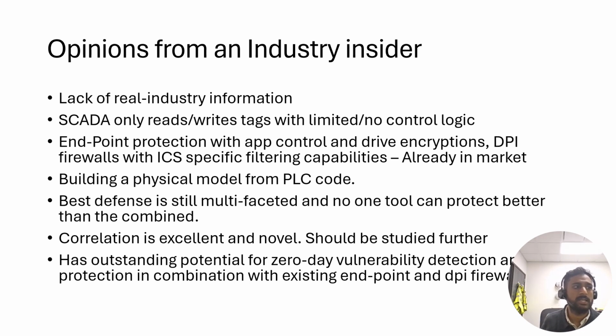One of the other challenges is building a physical model using PLC code. Programs are not always written in one language, definitely not always in function block diagram. It's a combination sometimes. And even if a standard was used, it would be quite challenging to build a model, especially in factories and plants that use multiple PLCs to control multiple sub-processes that are dependent. Such as in a water treatment plant, there are multiple processes that have links. Some of the things are running in manual, some of the elements are in auto. It would be quite unpredictable, and it would be very challenging to build a model. It remains to be seen how effective Scaphy would be in a plant like that.